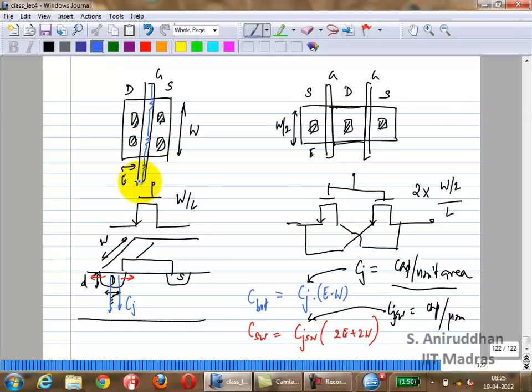you are basically routing, because what happens is the gate connection you make is somewhere up here, right? The transistor stretches all the way, so you have a problem, right? Because instead of directly connecting to the real gate, the real gate is actually a distributed gate along this. You can think of the transistor as being split up as multiple slivers, all of them in parallel, right? The last guy has a very, very large gate resistance. How would you solve it?